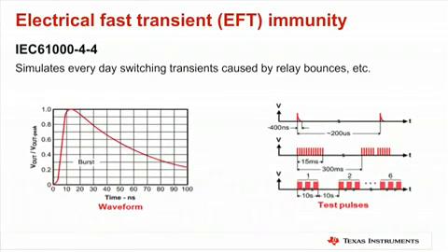This test requires a minimum of 10 discharges of each positive and negative polarity. Many equipment manufacturers consider the ESD test the lowest priority of all tests since its occurrence is limited to installation and maintenance work on I/O modules. During these activities, operators should wear ESD protective clothing and intentionally discharge themselves prior to any contact with the module.